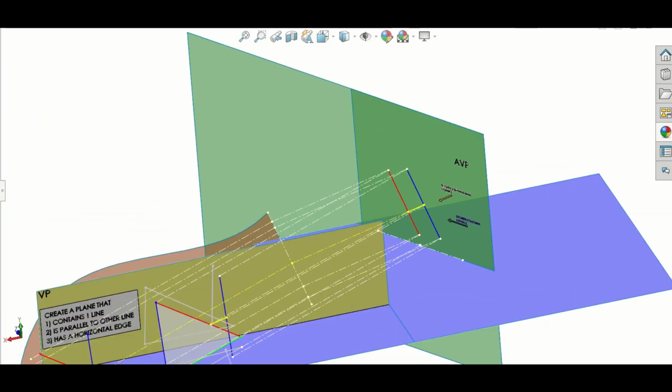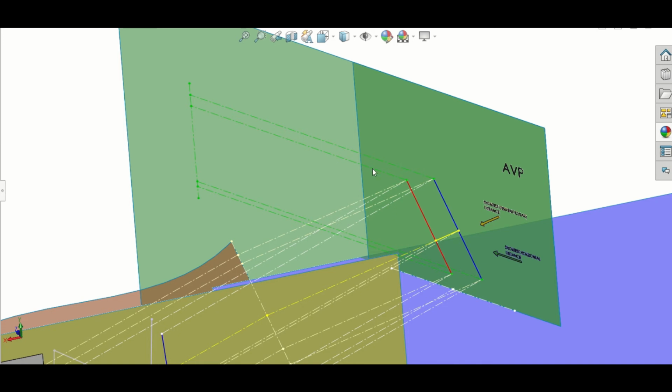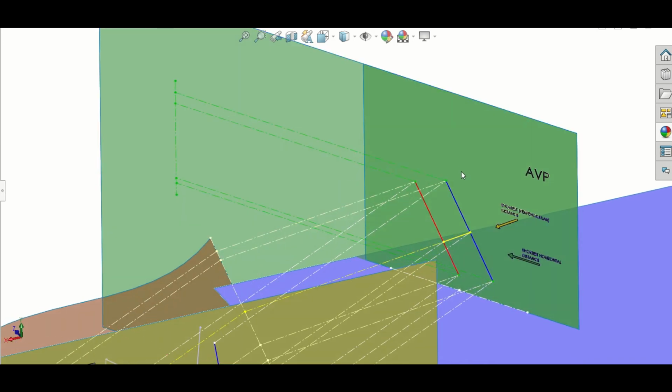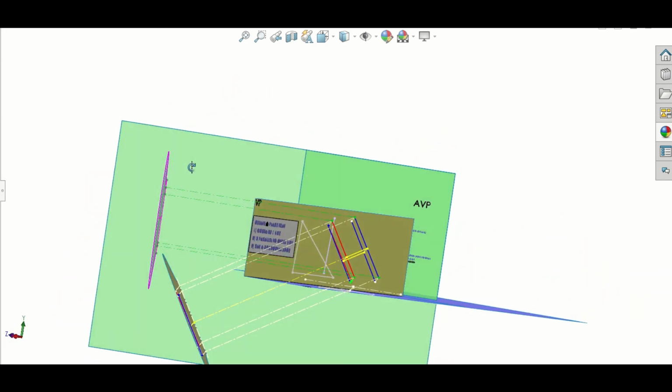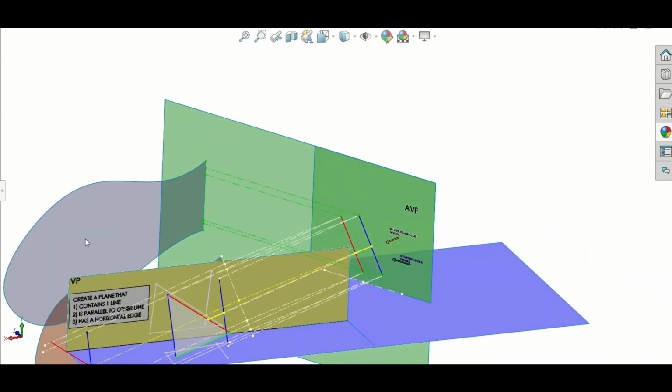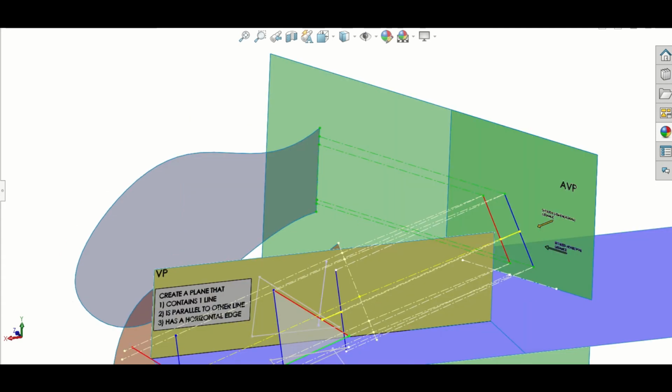So let's project. We project across in line with the x1, y1. Hard to see it here, maybe in green, but in line with the x1, y1, and we pick a point to stop for our next plane, and there it is. That's the plane. It comes straight out from the first auxiliary vertical plane right there. We're just going to do the same process as before. It's just a different viewing direction, and that's all. So the green lines come out. My distances come back from the plan, the distances from the auxiliary elevation back to the plan marked out here. And we get our red line, we get our blue line.